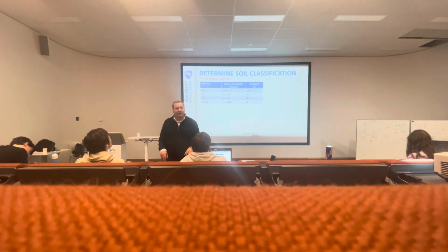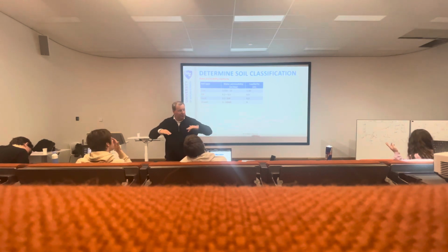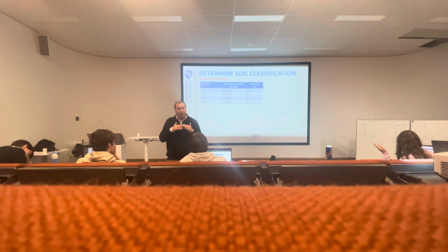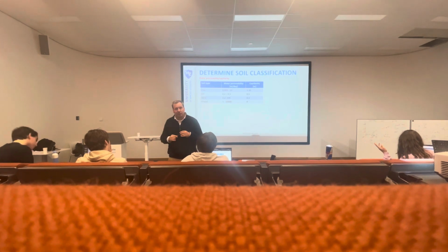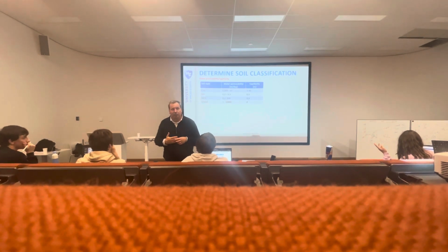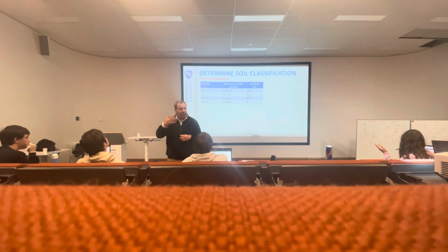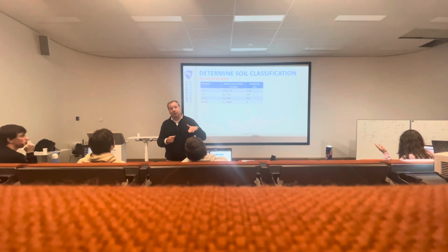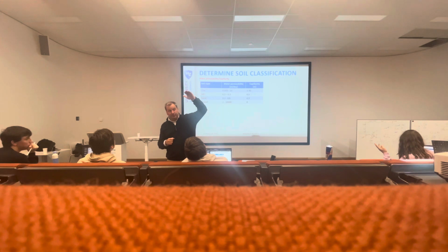Then we have the capillarity, and capillarity means the ability that water is being pushed upwards. Due to the fine pores, water has the ability to go vertically upwards. It's the same as when you have a straw and you drink something, it's very small, you create a vacuum and it comes up. And with clay you can see the groundwater level can be minus 30 meters, but still it can reach the surface.